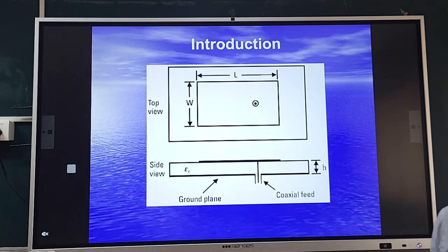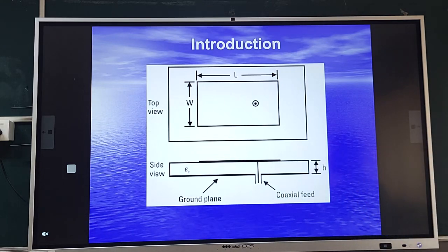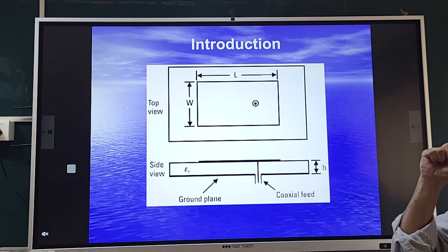Again, how much larger? As I mentioned in the radio frequency design course, everything in microwave, everything in antenna design is wavelength specific. Okay, how much thicker? How much thicker in terms of wavelength? Remember, a 1 mm thickness is not that much thicker at 900 megahertz, but 1 mm thickness at 9 gigahertz is a very large value.